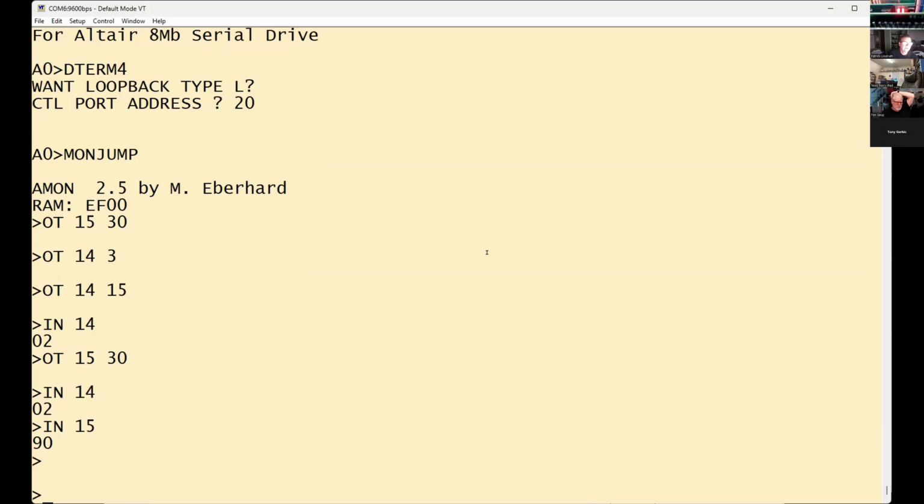Hey, Walt, either you don't have a loopback connector in there, or this 2SIO is not able to receive. I mean, the chip isn't even seeing the info, so I don't think it's a bus problem or a computer problem or anything, because that should show 3, not 2. So the SIO itself is not even seeing receive data. So either the loopback isn't right, or I don't know what. Can you show us where the wire is on your loopback? Oh, I think he's using the cable now. He's got transmit data, receive data.